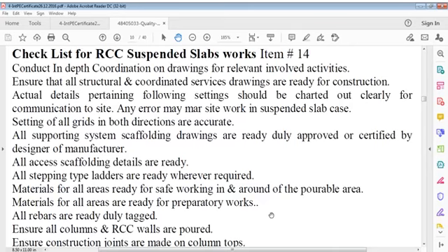And that one is very, very useful. We have to understand all services. We have to understand distribution of light in the room. So where should our light points be and where should fan points be, so that air is given all the time.